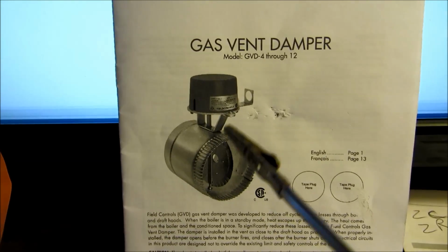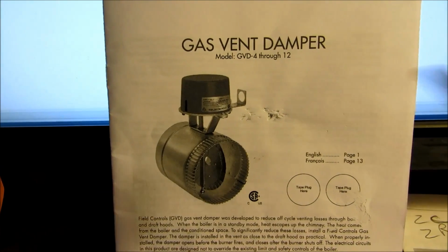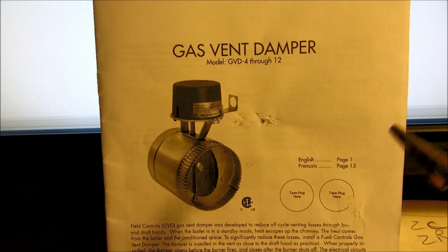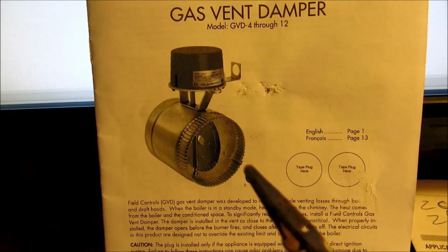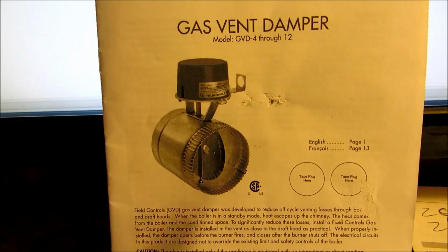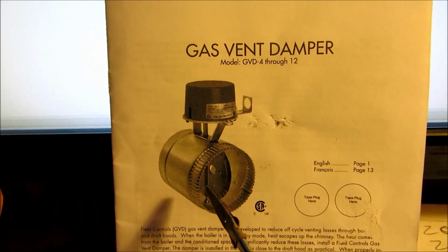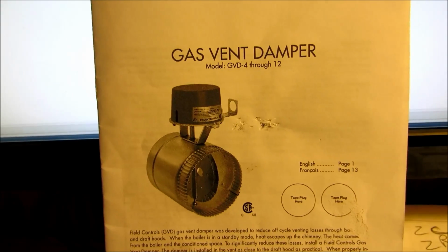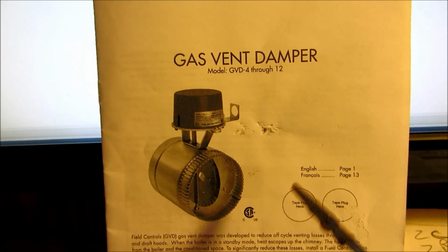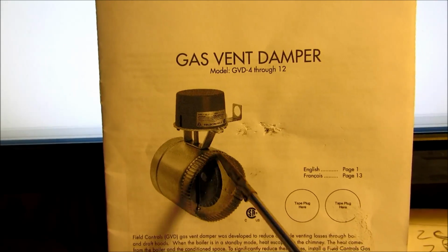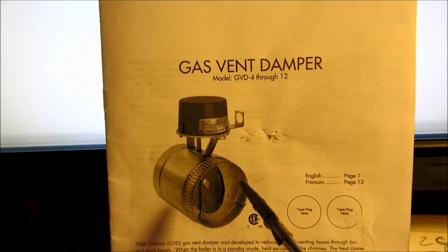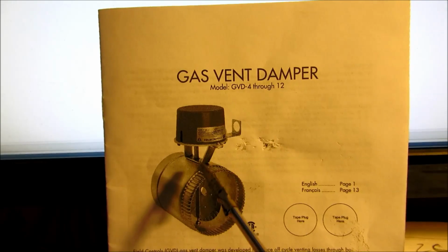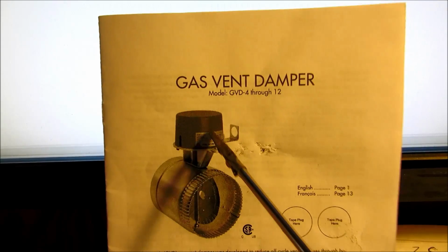Okay, on the vent dampers, it'd be strictly gas. How this works is, on a call for heat, it'd send power down here. It'd be a cold start boiler, a gas boiler, on something like this. Your circulator would kick on, then this vent damper would open slowly. When it opens all the way, there's an end switch in there, and it sends power back down to fire up the burner. So if for some reason this isn't opening all the way, sometimes these things go bad, you can just grab it and turn it by hand. If the boiler fires while the circulator is running, you know this vent damper is bad.